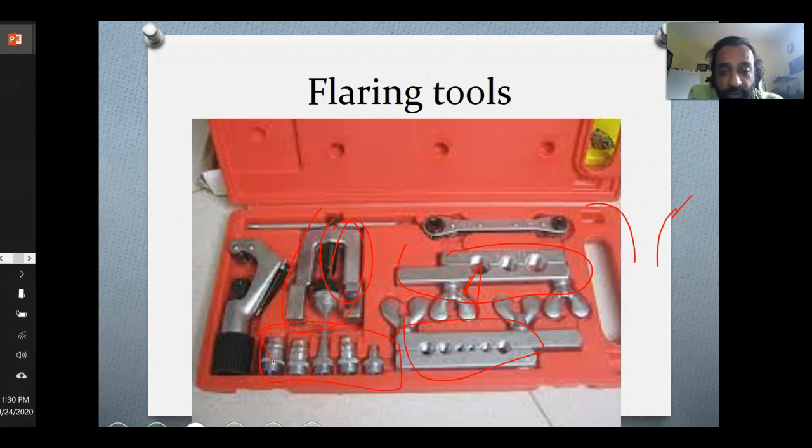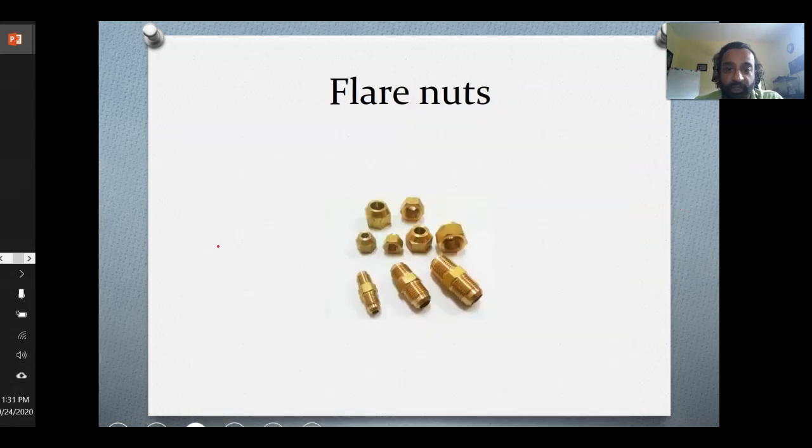In here you see the swedging tool. Swedging is basically making one pipe a little bit bigger, so the same pipe will fit right into it and you can weld. It's a good way to connect pipes without any pre-made fittings. And here is the cutter, and as I said, copper pipe is very soft, so be very careful when cutting that pipe, because if you do it very fast you might crimp the pipe, and if you crimp the pipe or bend it more than you need to, it's better to start with a fresh pipe than to try to fix it again.